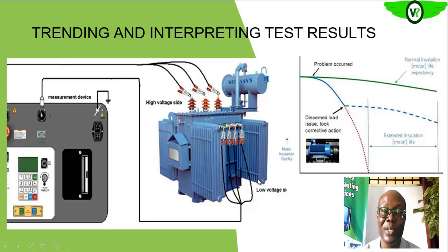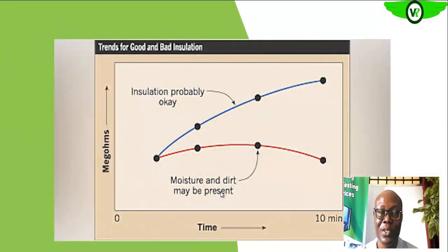So that is the importance of testing, recording your test results, and trending your test results to ascertain when there are deviations or when things are becoming abnormal, or to ascertain when you are entering the PF region of that particular parameter that you are measuring on the equipment.